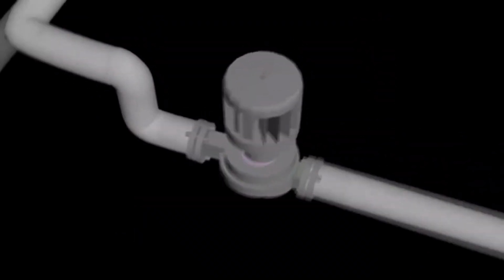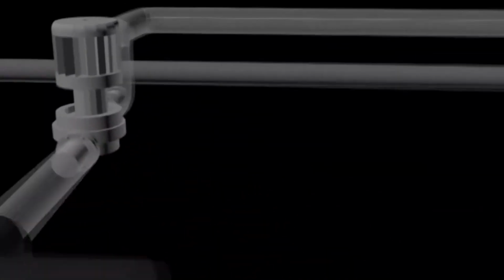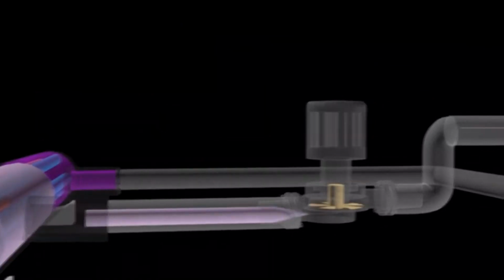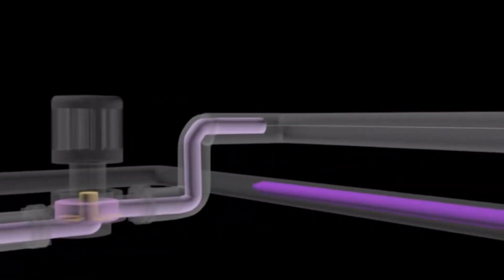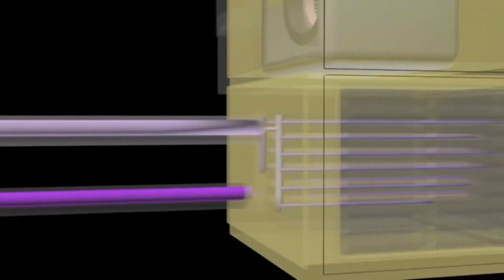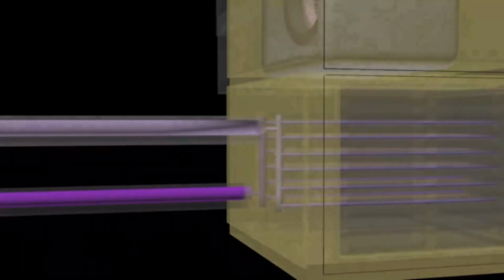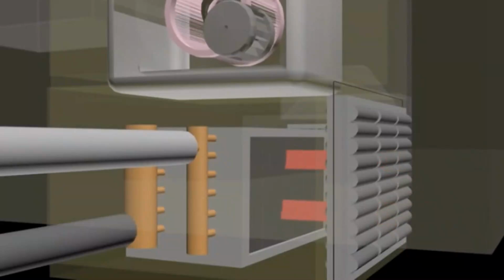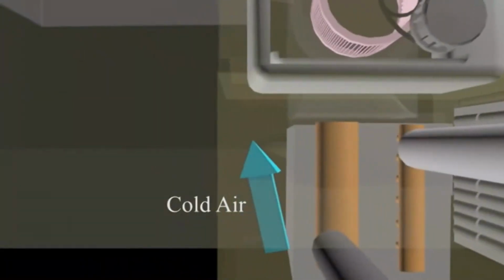Chilled water produced in the evaporator will flow into the air handling unit through a pipeline which is marked with dark blue color. This chilled water is known as chilled water supply. In the air handling unit, chilled water will then pass through the cooling coil. In the cooling coil, the hot air will go through and switch to cold air due to the heat transferred to chilled water.